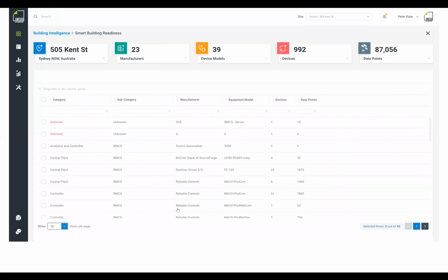Are all the ports in place? A classic example of this is where we connect to a building system, we have the BACnet, a vendor has said that the BACnet is there and it's enabled, and then we find that the BACnet ports haven't been commissioned on the network, or the BACnet has not been enabled in those subsystems. So this is a great way to start.